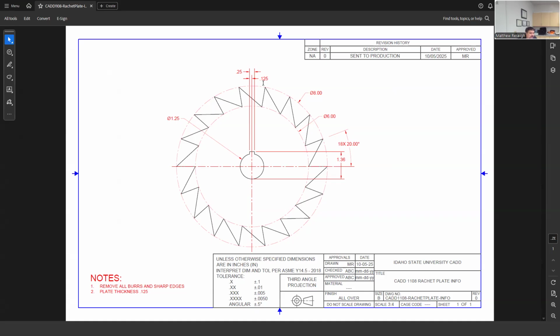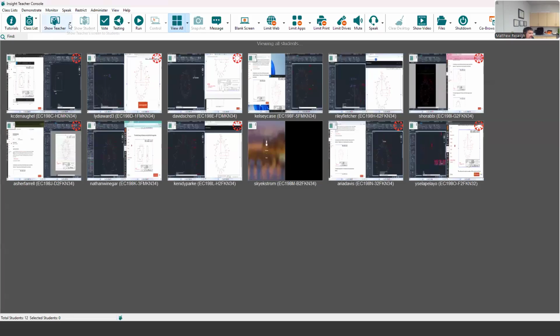It just shows the general location of keyways and key seats. That's why it maybe could be omitted in the future, like in an experienced shop, because they'd say it's always centered, we know that. We don't do off-center. There could be some weird reasons where you would, but generally it's understood that keyway key seats are going to be clocked, at least when they're designed, at either 12, 3, 6, or 9, right? And okay, cool. Excellent.